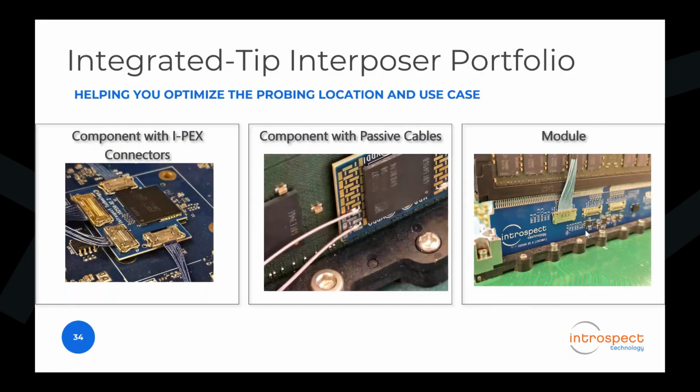So this allows us to get into the LPDDR6 and DDR6 regimes. But let's say you're on LPDDR5 and you're looking only at the CA bus, then the SV7C can have the exact same GUI that we showed you, the same interposer, the same RSH, and you'll be able to do a lot with the CA bus.